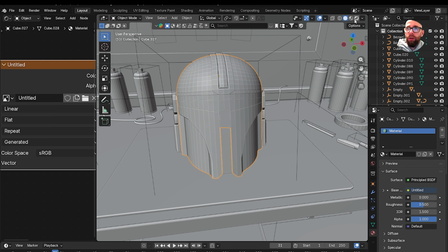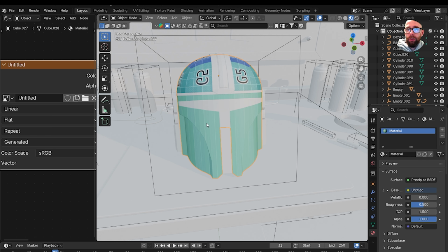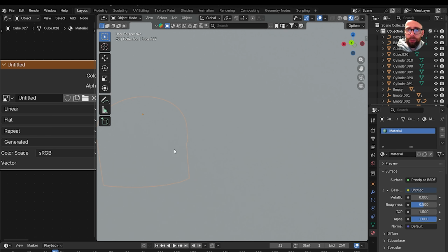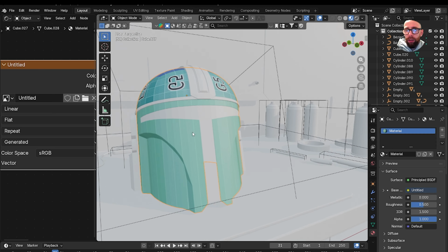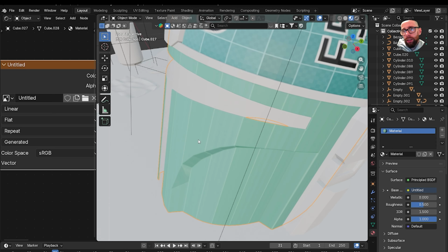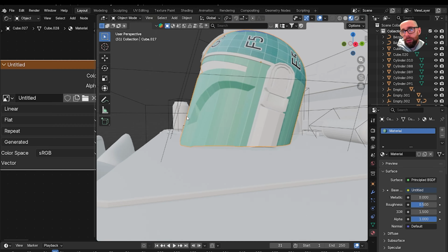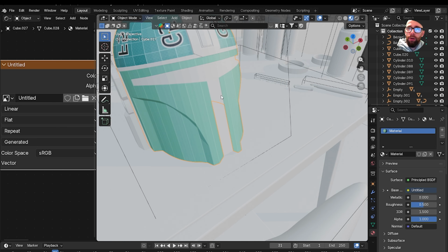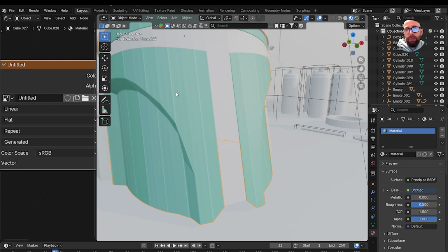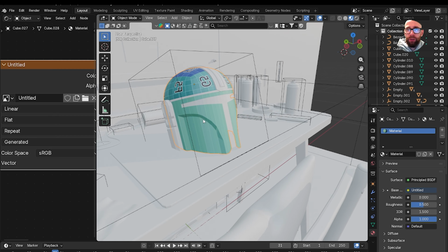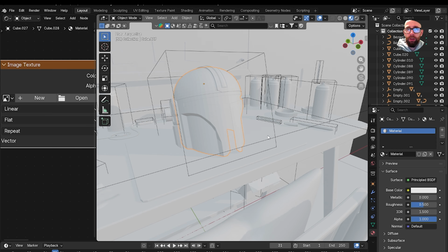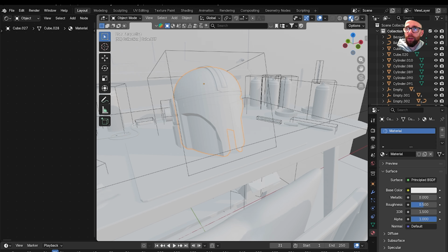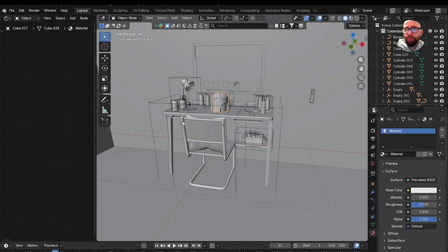The third one along is material preview. If you click on there, you'll see we've got some weird distortion on our model. What we're looking for is perfect squares everywhere, which we've got okay here, but we haven't got control over it along here. So what we need to do is tell Blender how we want to lay out the material, and we do that with UV. So I'm just going to undo all of that and come back to preview.